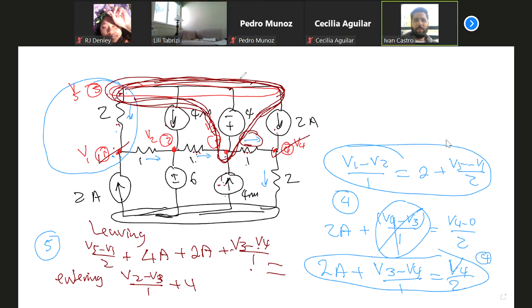But you have to do that since it's an independent source, right? Dependent or independent, it's a voltage source and you don't assign current to a voltage source in nodal.